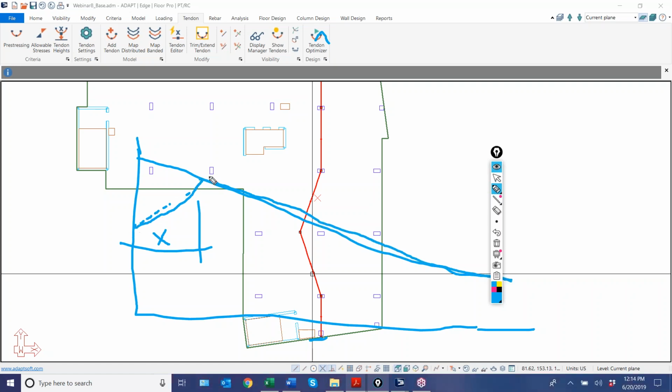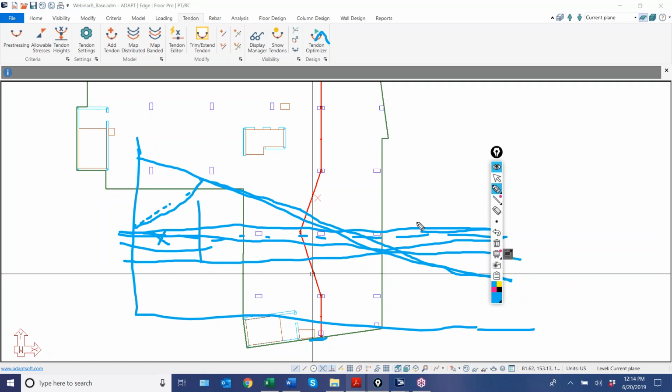So this is the actual diagram for the force, and we're just going to assume that our effective force is somewhere in here. It's just the average of this set of numerical values along the length of the cable. And then we also have to offset this number. This is just a flat line. We have to offset that for long-term loss. So this delta here, which is constant along the length, is just the long-term loss that we assume as part of our effective force value.